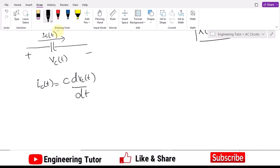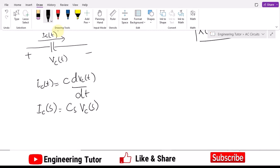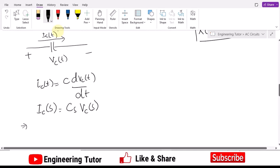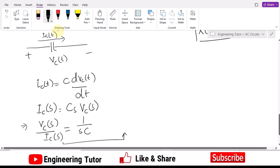Now again taking the Laplace transform of both sides, I will get Ic of s equal to C, the derivative term will be replaced with S, and it would be Vc of s. Now rearranging it, I will get Vc of s divided by Ic of s equal to 1 over S C. According to Ohm's law, this is also the impedance.